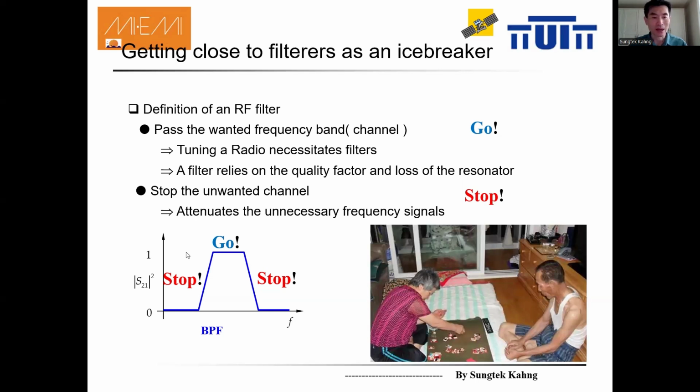As you see, the transfer function of that black box, or communication system, is represented by the transfer or transmission coefficient of the system, from devices to modules or subsystems. We are used to using S21. This is the transmission coefficient from port 1 to port 2, where ports 1 and 2 mean the input and output ports, respectively.